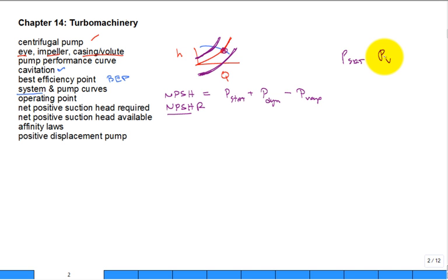If it's warm fluid, you're going to have a harder job to stay away from or avoid cavitation, because typically when it's warmer, what's higher in this equation? When it's warmer, the saturation pressure. This is a function of temperature. Okay, what is another name for the sum of the static and the dynamic pressure? The what pressure is called the static plus dynamic.